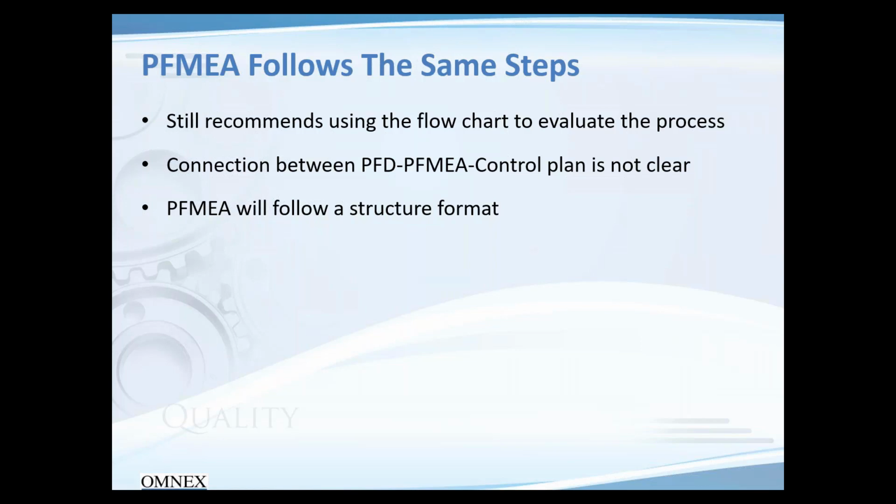In this new method, you can establish causal logic that would say for this failure mode to occur, it may take three of these causes occurring simultaneously. So almost similar to a fault tree analysis. So look at this new system as kind of being a mesh between the current FMEA system and fault tree analysis. It has kind of the same features.